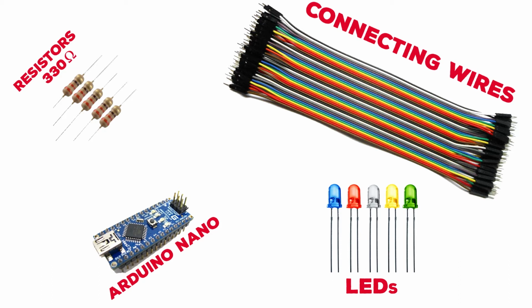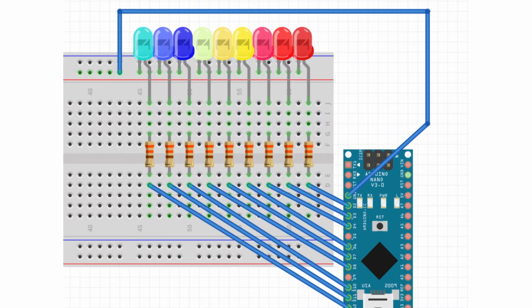So let's start connecting. At first we are going to attach the power lines to the breadboard. Firstly we are just going to attach the ground to the power line, as it is what is needed as of now. We won't be requiring the extra 5 volt as we are using the digital pins to trigger individual LEDs. We are going to use 330 ohm resistors to limit the current flowing through the LED.